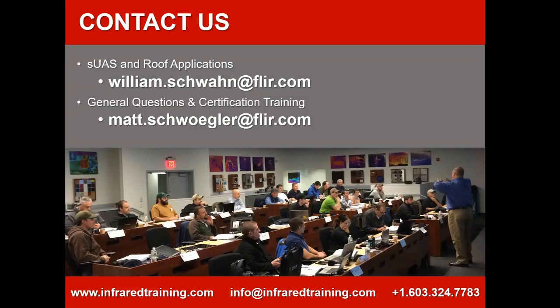Justin, good question. Usually moisture performance issues are going to be non-symmetric. So if we have insulation issues, you'll see gaps in the insulation, in other words, straight lines or blocks of missing insulation in the foam underneath. Or if there's insulation underneath the roof deck, again, moisture is not going to be symmetrical. So sometimes it's a challenge to tell the difference. But the other way to tell that difference is to use other methods. In other words, use a non-penetrating moisture meter to see if it's moisture or heat loss.